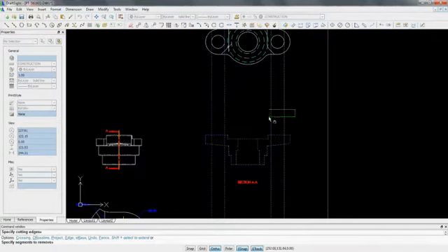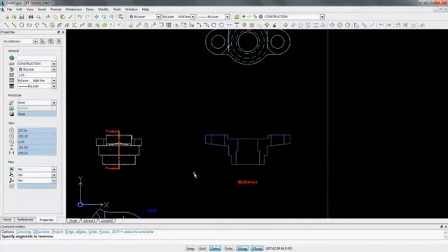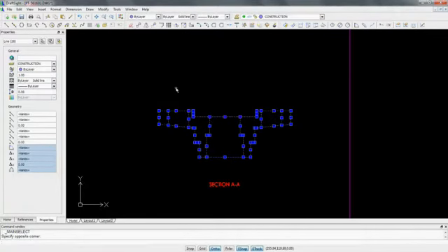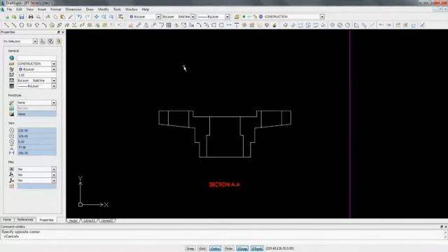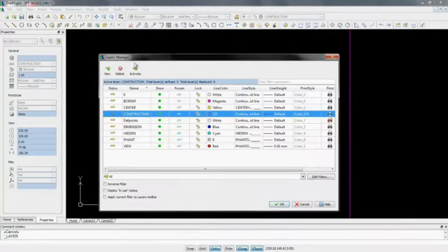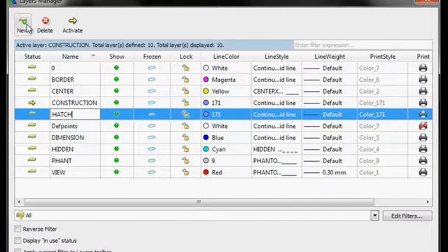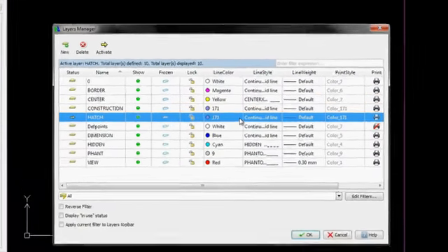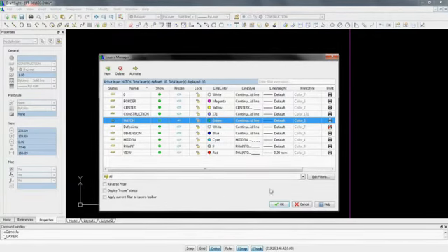All of this geometry was created on the active construction layer, but changing the layer is quick from a list of properties available for all the selected items on the left-hand side of the screen. You can also add as many layers as needed from the Layer dialog box. Just press New, give it a name, and even set it as the active layer at the same time. Then just make any required changes, such as the color in this case.